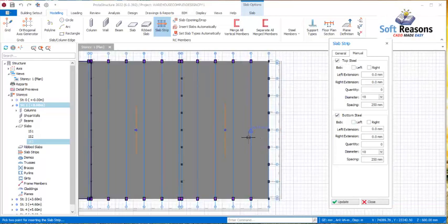Okay, so basically, slab on grade, we normally design it with only top and bottom bar right there, because it's not carrying any load. It is when it is actually carrying loads that we design it, sometimes based on analytical results, which we get using finite element analysis.